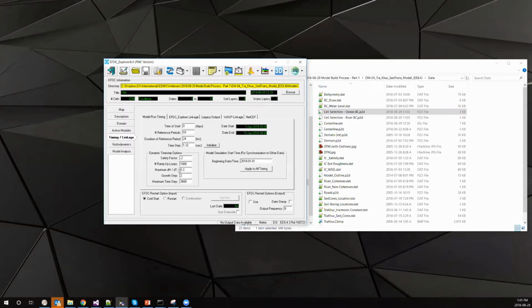It's a little confusing, but it's important that you recognize that when auto stepping is turned on, the time step that's shown here is actually the minimum time step allowed. In other words, my actual time increment for a particular time step would have to be in multiples of this value.